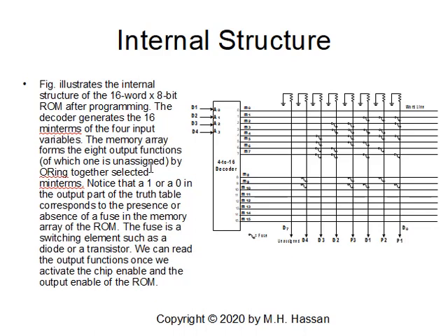So once you burn it, you take the EEPROM, you put the power supply, and the chip enable and output enable have to be grounded. The two supplies have to be connected to the chip. And after that, you apply the inputs, any data you have, and you take the output maybe to LEDs to see the Hamming code, because this is a Hamming code generator, for each function. Well, those inputs could be supplied from a counter, from a register, from another place, and automatically you have the code converted to a Hamming code, and the Hamming code can be used for communication purposes.